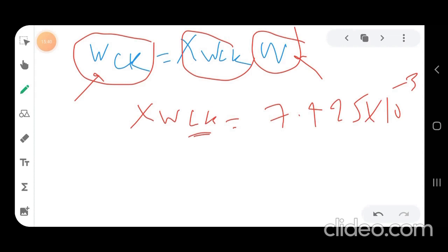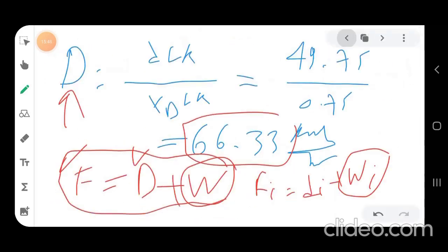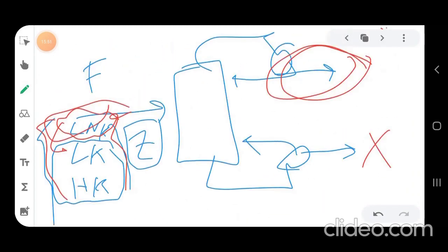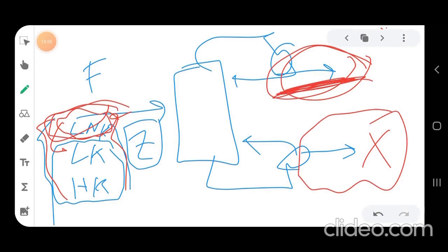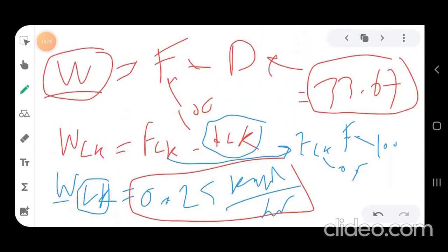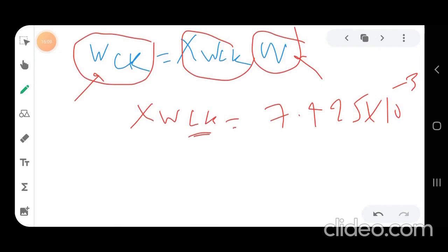And now it's a critical point that I want you to understand. Let's go back to the diagram. As this light key will be totally recovered here in the distillate, what we will have in this waste? We will have only the heavy key, isn't it? So you can say with confidence that x in the waste of the heavy key will be 1 minus x in the waste of the light key.